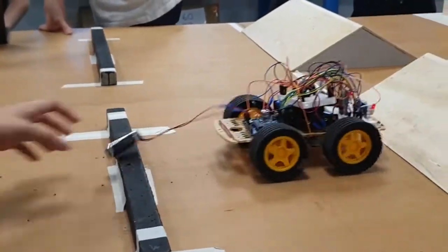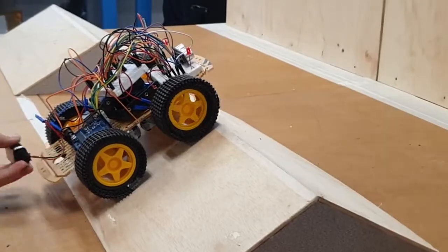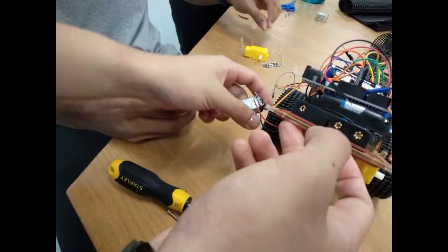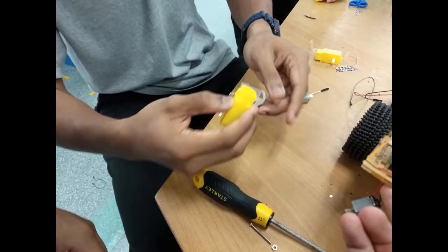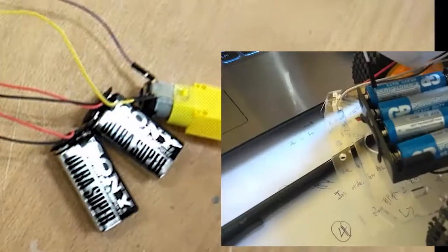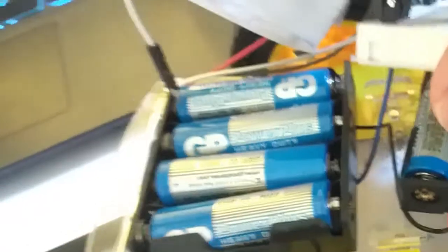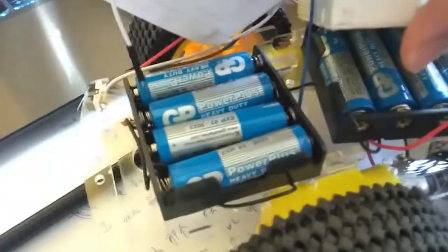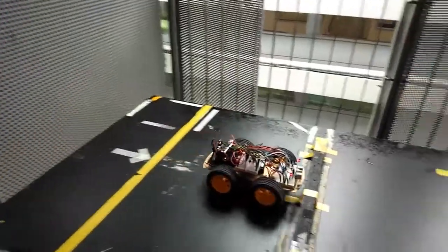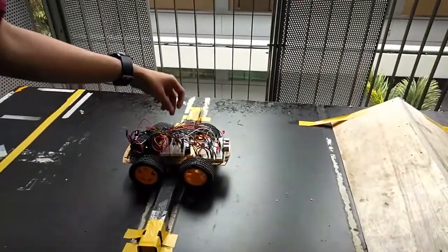Our robot would still occasionally fail to clear the second obstacle. To tackle this, we used a higher gear ratio gearbox in order to increase the torque. We also changed our motor power source from 2 9-volt batteries to 12 1.5-volt batteries in series to provide more power. Another difficulty is that the vehicle would stop earlier than usual due to inaccuracies of the ultrasonic sensor readings.